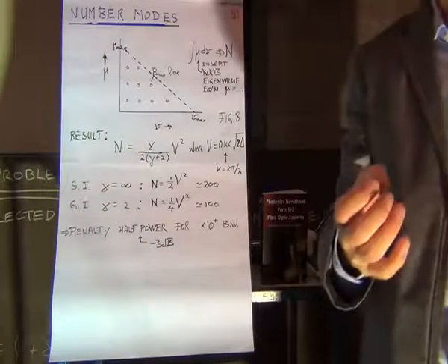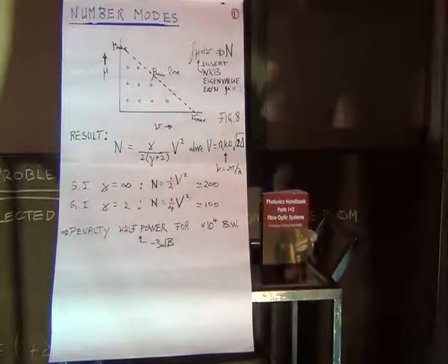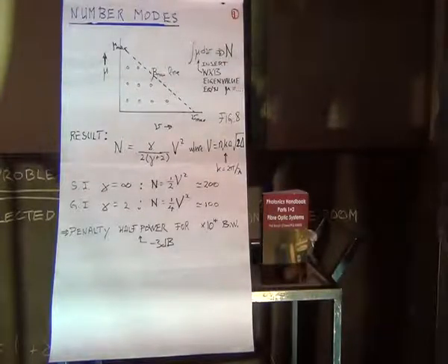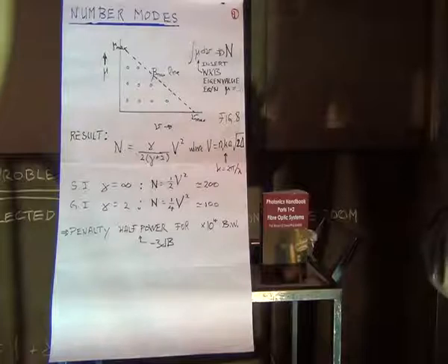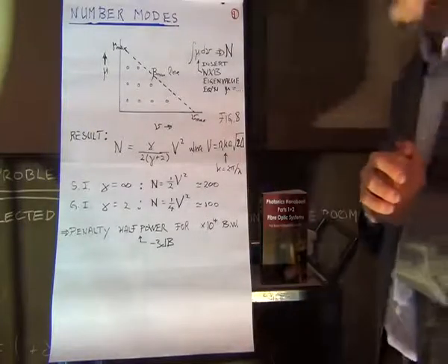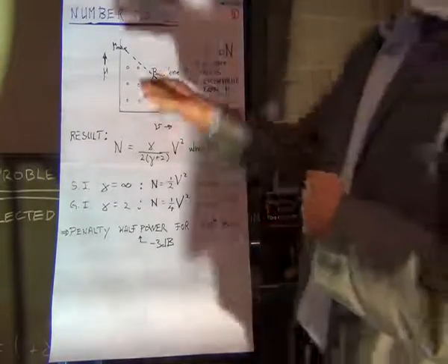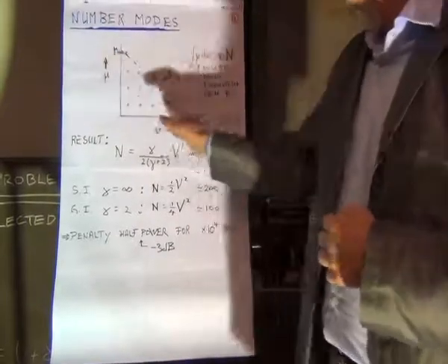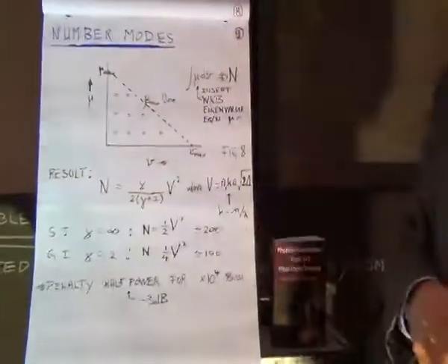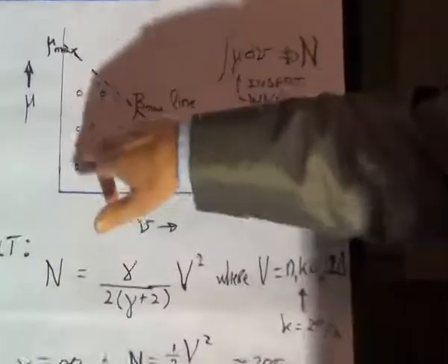Okay, so there are two integers for each mode. We call them the LP modes, and you put the two integers as a subscript, LP subscript nu mu. If we draw a graph of nu against mu, we get a set of dots because they're integers.